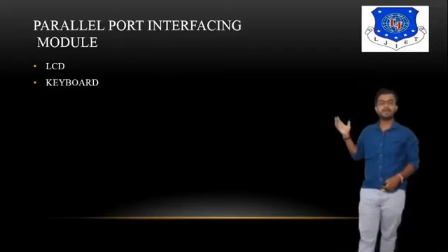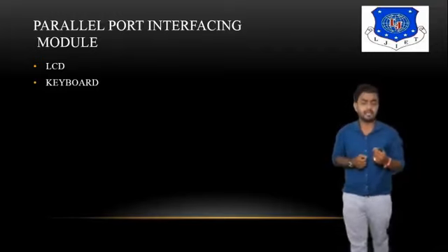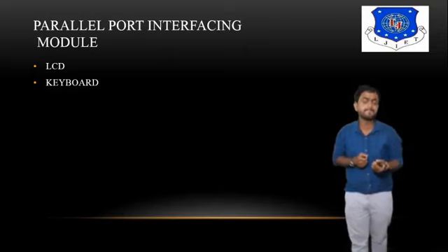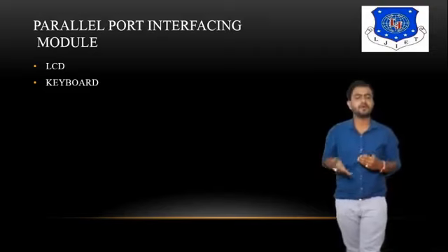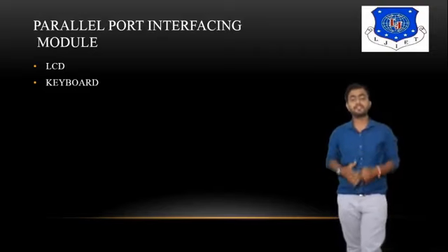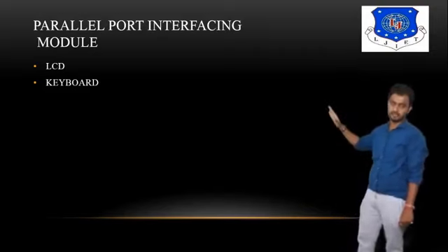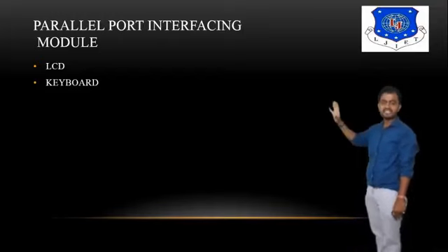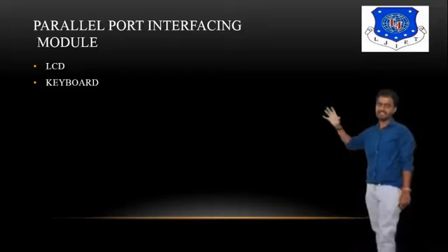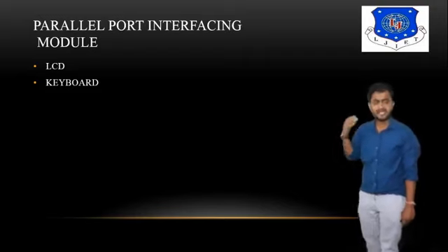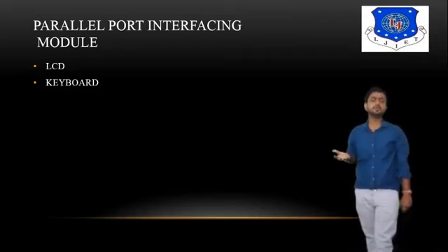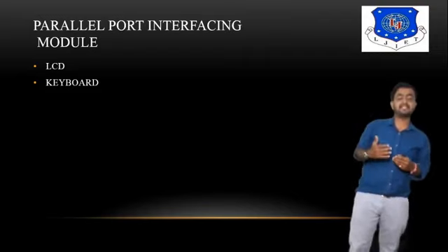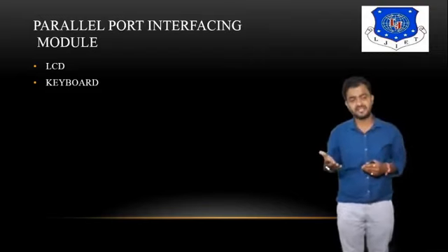Similarly, for the keyboard, we use PS2, and a 4x4 keyboard matrix is there. So there are a number of matrix modules. In that, we use 8 data pins for the row and column operation. So these are the best examples of parallel communication. If you're talking about any LCD, it basically comes with parallel communication. But right now, a few LCDs are based on the I2C module also. So there are only 2 data lines, pins SDA and SCL, which we have already seen in the previous session.